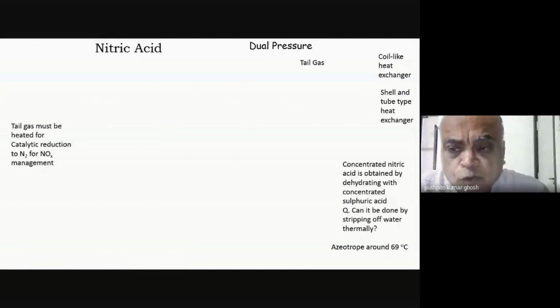Okay, so let us go through this process step by step, because we had found when we were talking about ammonia that you can isolate ammonia as liquid ammonia, right? Last time we discussed that, and that's the easiest way to recycle all the rest of the gases. And because the ammonia is pressurized in the Haber-Bosch process, you really don't have to lower the temperature extensively. It's a reasonable temperature range where it liquefies at 200 bar pressure,